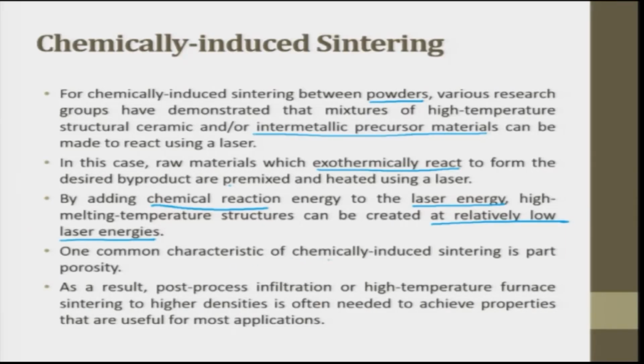One common characteristic of chemically induced sintering is part porosity, which is very important. As a result, post process infiltration or high temperature furnace sintering to higher densities is often needed to achieve properties that are used for most applications. Infiltration means, let us assume you have a bush. This bush is made out of abrasive particles. You are making it by a sintering operation, and if you see here, there are a lot of porosities. These are all abrasives. You can see a lot of porosities there.